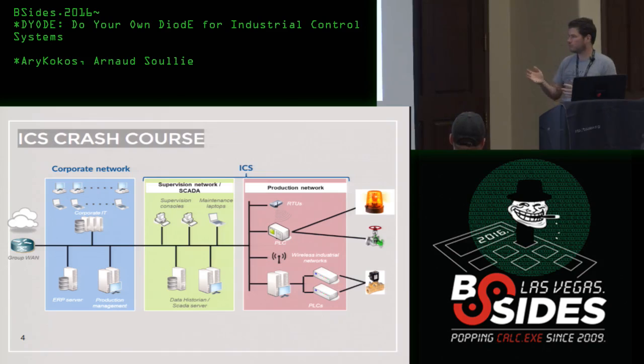That means, for example, the PLC can be used to, if I take really the most simple example, you can wire, let's say, a switch to the inputs of the PLC and wire a light bulb to its output, and then you can program the PLC to switch the light on when you flip the switch. So of course, that's a silly example because you can do the same without the PLC. But the advantage of using the PLC is that if tomorrow let's say your industrial process changes, you just have to reprogram the PLC. You do not have to rewire everything. So that's why we use PLCs.